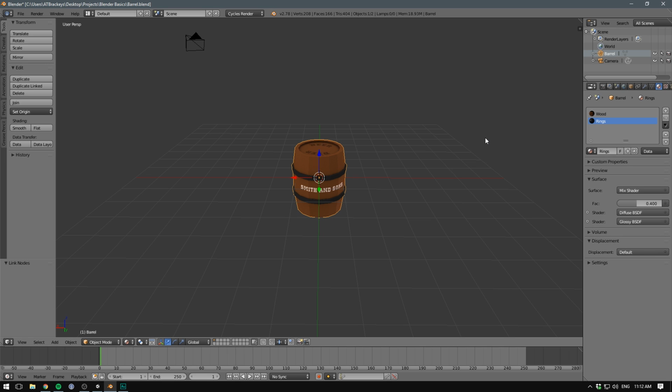However, these lights are actually used in the Blender render engine and not for cycles. In cycles, we have a much more realistic approach to lighting. That means that in order to create a light, we first make a surface that should emit light, and we then apply an emissive material to that.